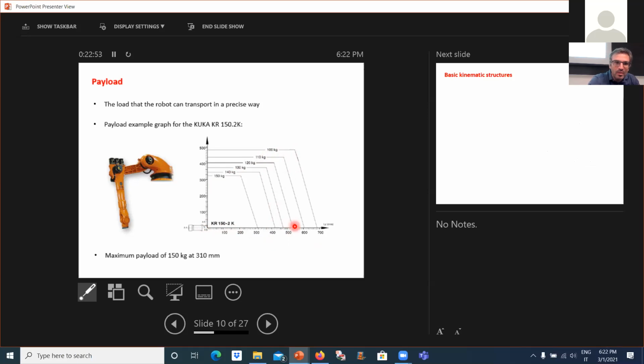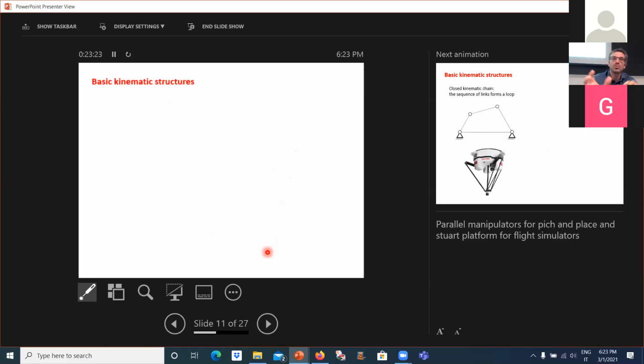And for hydraulic robots, the payload that they can sustain is very high. That's why hydraulics is interesting in robotics, because of the capability of having a very high power to weight ratio. So in a small actuator, they're able to be very powerful and develop a very high torque and a very high velocity at the same time. While with electrical motors, you need to have a trade-off. Either you have high torque and low velocity, or high velocity and low torque.